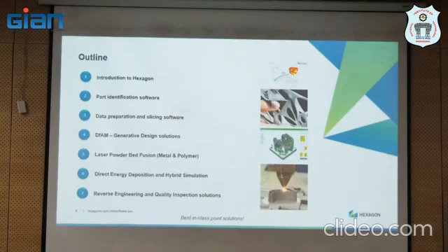So now if I replace the existing material with the 3D printed material, what will be the difference in material property? If I come to know that, the rest I can easily calculate. If I am reducing my yield, what will be my fatigue life, or what will be the performance of the 3D printed material? This is very critical. In fact, we have limited resources or knowledge available on 3D printing. So it is very hard for somebody to directly say yes, this part can be easily replaced with 3D printing technology. The other part is cost.